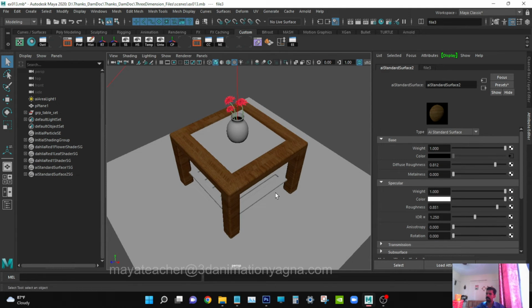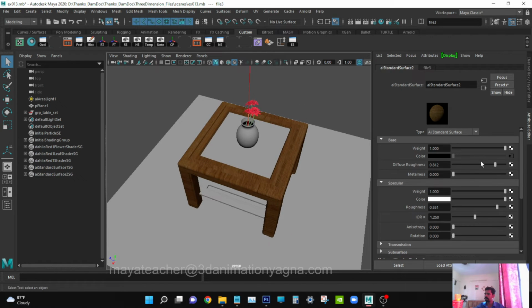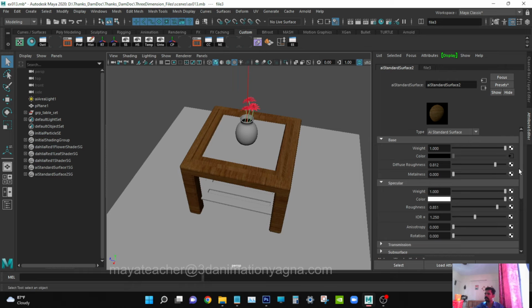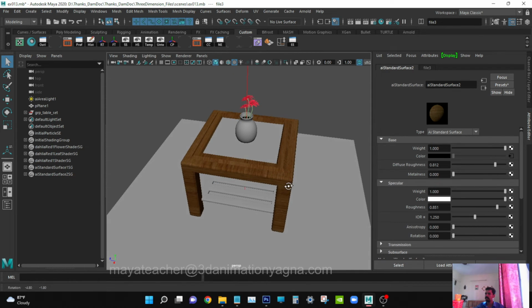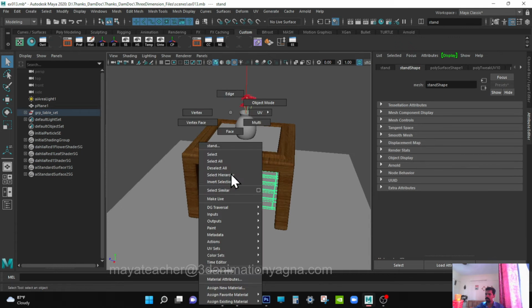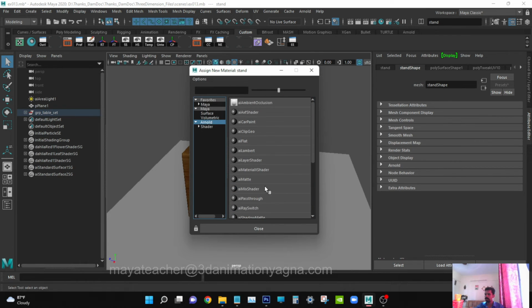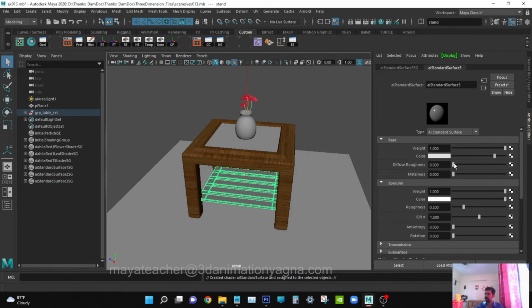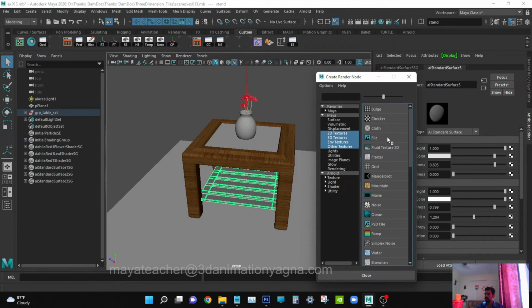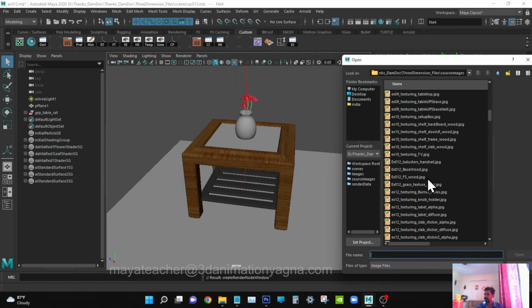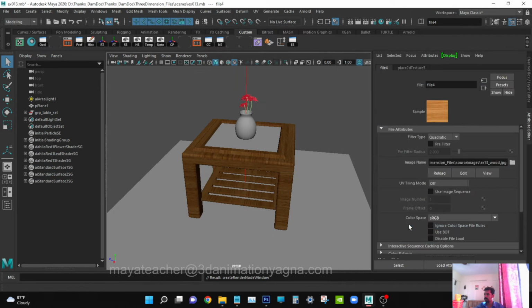If it needs, we can do variations in the shader. If you want some different color for this border, glass border, you can do that variation in the shader. For this also we'll give, this is the final. Standard surface, roughness, diffuse roughness 1.2, and the color channel, file, image name, good, we are done.